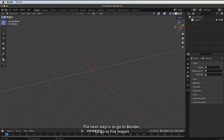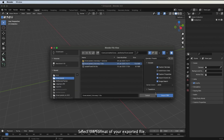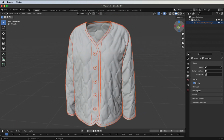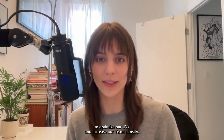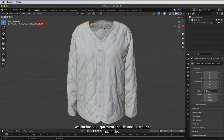The next step is to go to Blender, so go to File, Import, select the format of your exported file, locate your file, and import into Blender. Our 3D model is now in Blender, which means it's time to optimize our UVs and increase our texel density. So here's the steps. When we exported our model from Browzwear, we included a garment inside and garment outside. These will be on different layers, so you'll need to repeat the following steps 2 times.